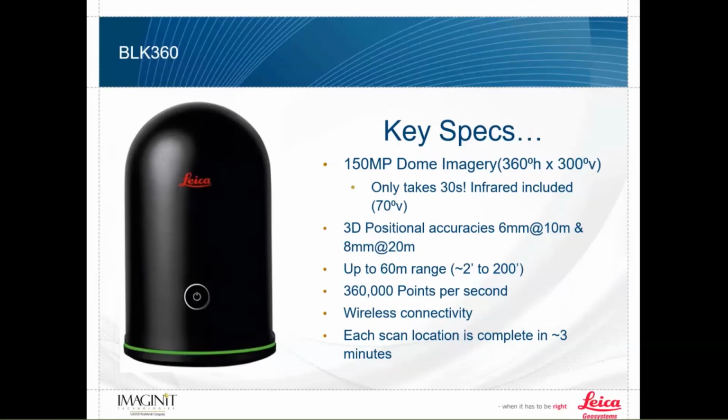Those things are going to have an effect on the amount of time it takes the scanner to complete each scan. You also may walk into a room and say, boy, the point cloud is more than enough information for me. I don't need it to take pictures. So you may not take pictures in a particular space. Those types of things are going to lessen the time it takes for the BLK to finish each one of its scans.